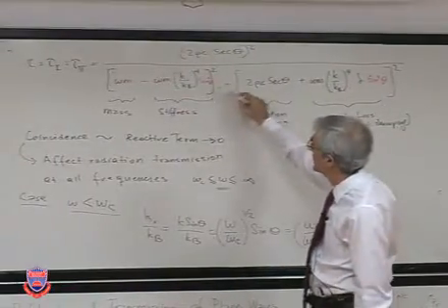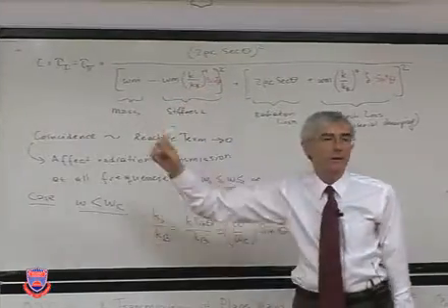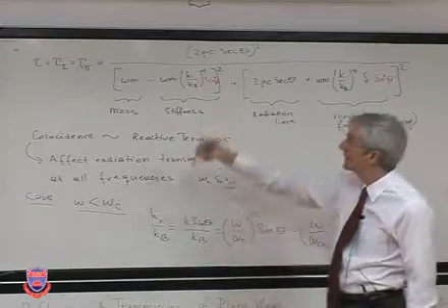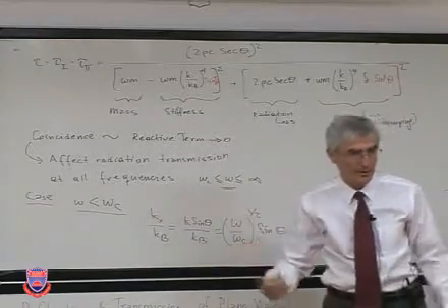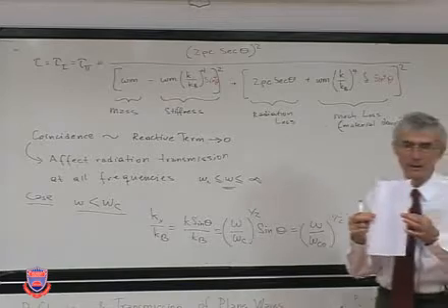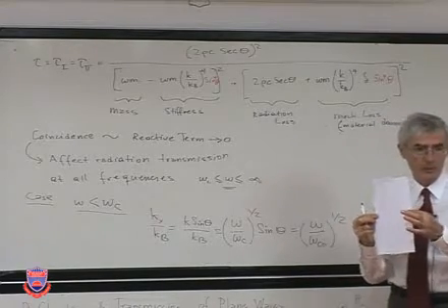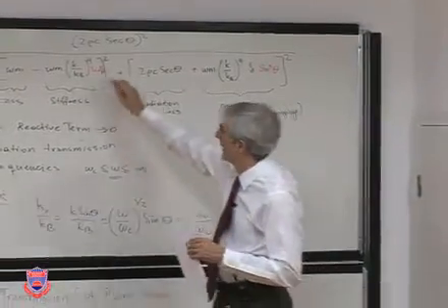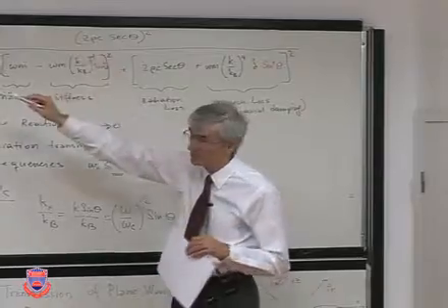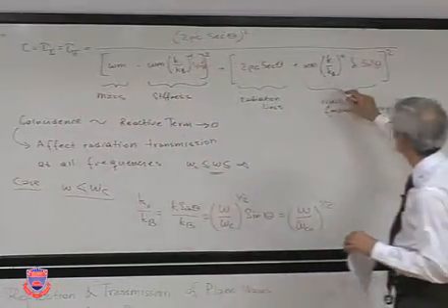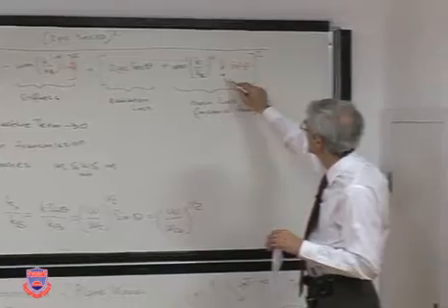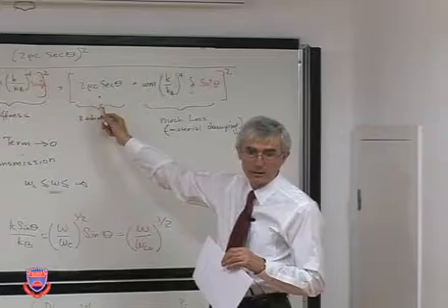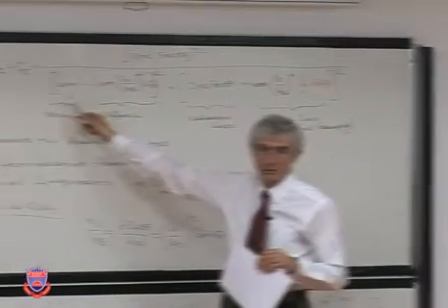First of all, everything is relative. When you say low, we don't give numbers, but with respect to, in this case, the coincidence frequency. And coincidence frequency is something that's determined by the thickness and properties of the plate with respect to the fluid medium. So if this is a negligible term, and also plate damping is negligible, we are left with this radiation term and inertia term.